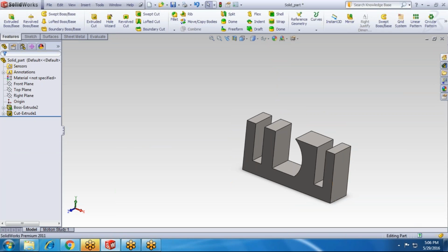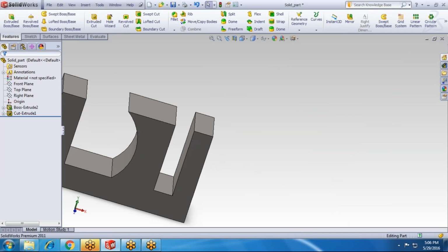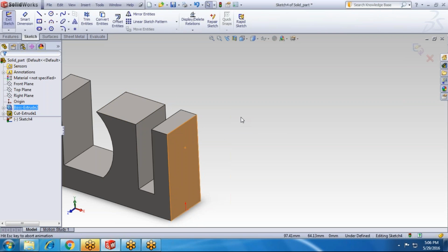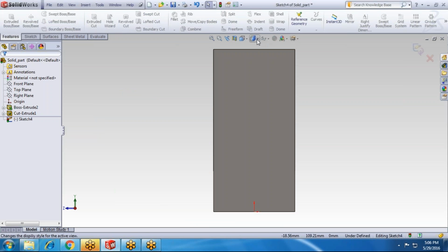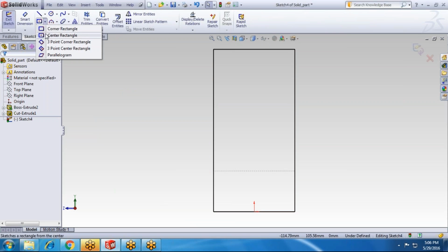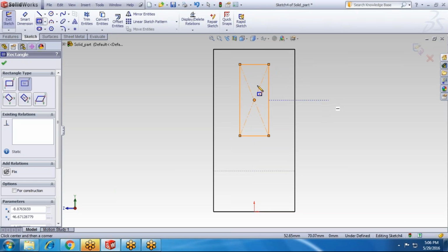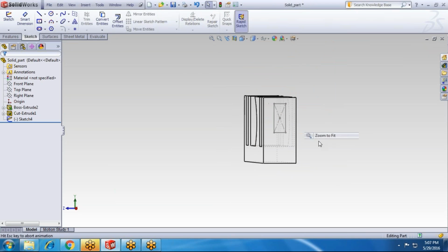So now next level will be there. I'm using the next command here, and the next command I'm using is extrude again, extrude cut. So I'm just picking the surface here. Now create a new sketch here, sketch number 4, control it, and now you see there the object will be in the hidden mode like this. I'm just creating a rectangle here inside the object, a 3D object.